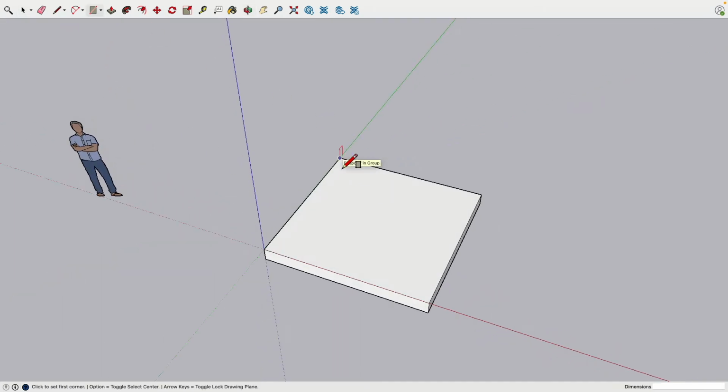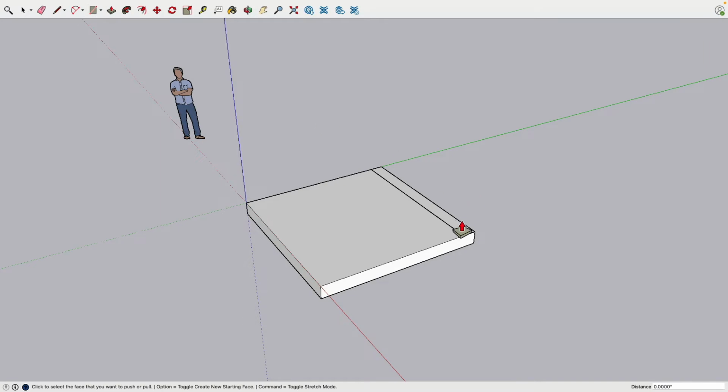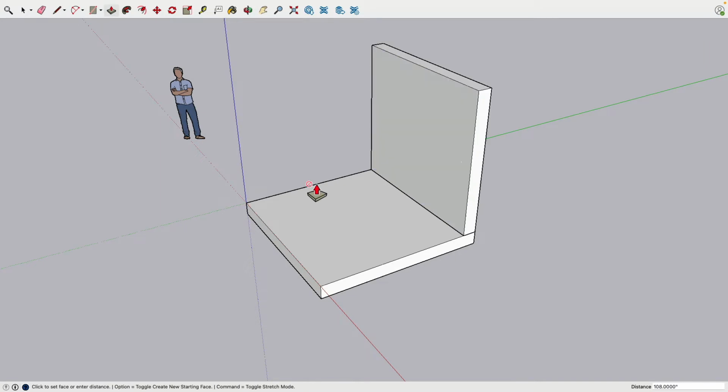Let's add a wall. So from the back to this corner here, I can see this is 120 inches, comma, 10 inches. We make this on purpose a little bit thicker wall. Oops, that was the wrong symbol. 120 inches, not feet, by 10 inches. There, very nice. And this we can now extrude up with push and pull 9 feet.